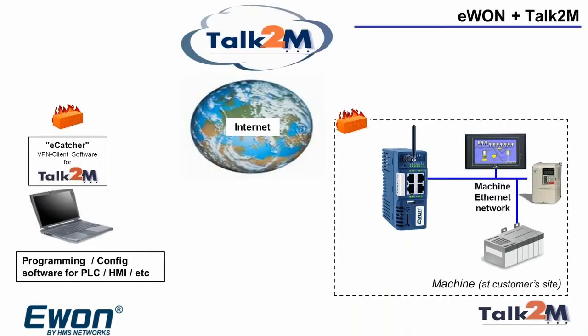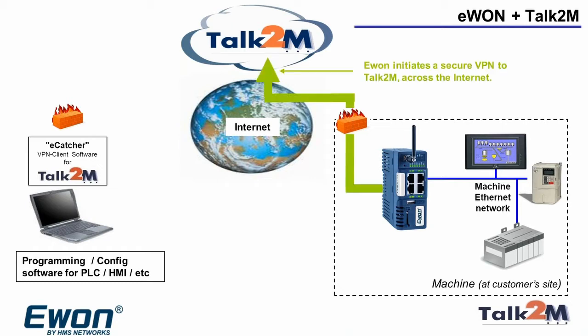So the first thing that happens is the Ewon device is connected to the machine network on site, and when it's powered up and enabled, it will make a VPN connection out to the Talk2M cloud. That VPN connection is an outbound connection from the site through the site firewall using port 443, which is a very common TCP port, out to the Talk2M cloud. And that VPN connection is held up as long as the Ewon is enabled.